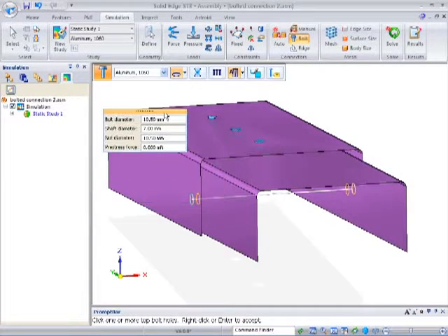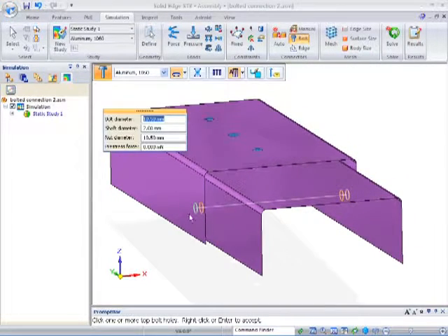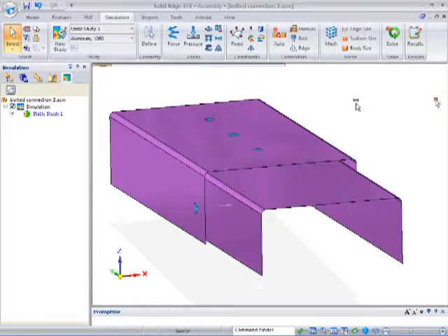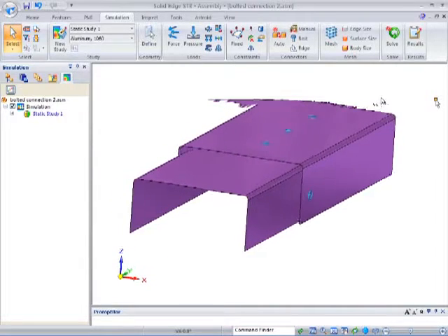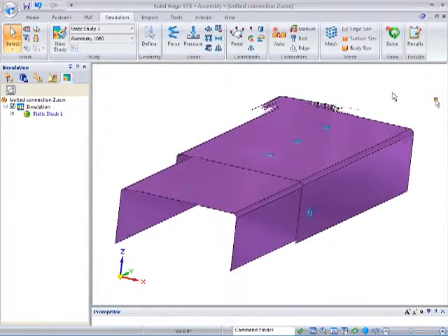The exercise here really is to show you that if you need to change that search distance so it doesn't identify all of those holes at the same time, you simply click and hold and drag that search value back a little bit graphically. Key in your pre-stress value, right mouse button click to create the connector. Now I've got 5 connectors created for this part.